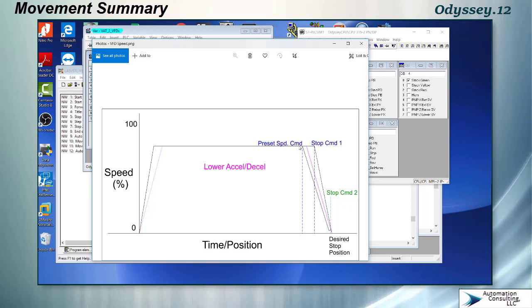So there's a big difference between stopping at 80% speed and stopping at 10% speed, and that is the entire reason for putting this preset in here. By using presets, you can use digital inputs actually to fire the presets. I moved the 10% and the 80% in here into the register, but you can just use a digital input to select the preset speed on the physical drive itself. So that's another method of controlling speed to do your creep to a stop.